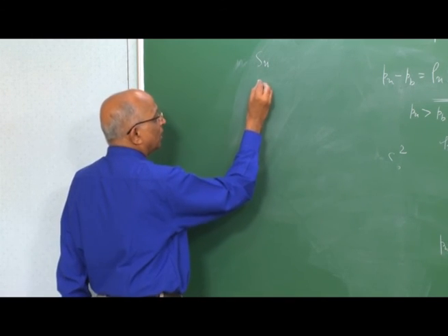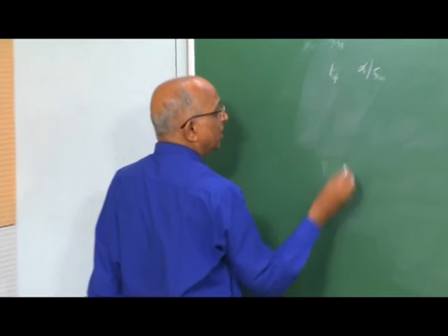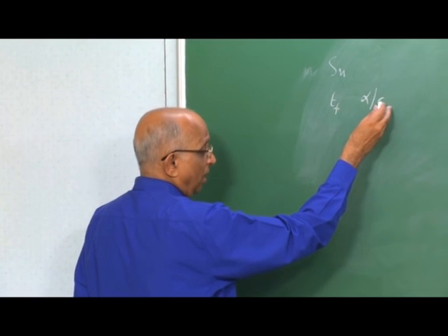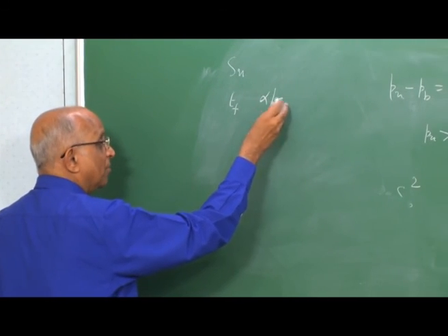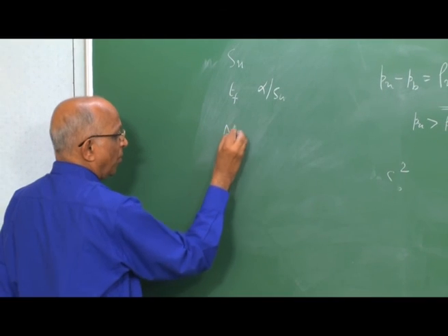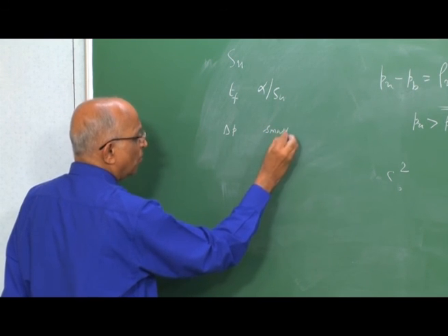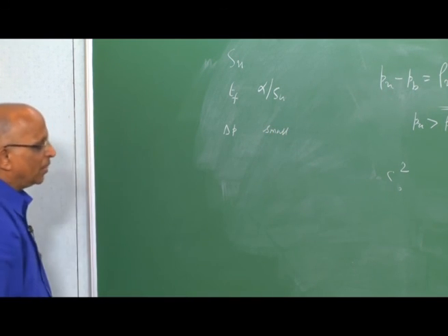We also talked in terms of the thickness of the flame, which we said is equal to thermal diffusivity divided by the speed of the combustion front, and also we talked in terms of the pressure drop across a flame, which we said is extremely small, but there is a small drop in pressure across the front.